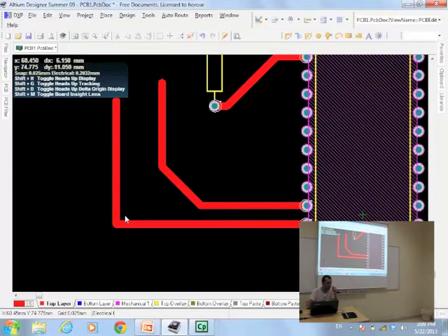And especially ground. Do not use a ground that goes around all over the PCB and comes back to the same place. If you do that, you make an antenna for the signal, or for the ground you make different levels of ground for your circuit. So this is not it. These are the simplest things of PCB, and in all of your studying in these 4 years of university, if you just do these things, it's fine, nothing more.